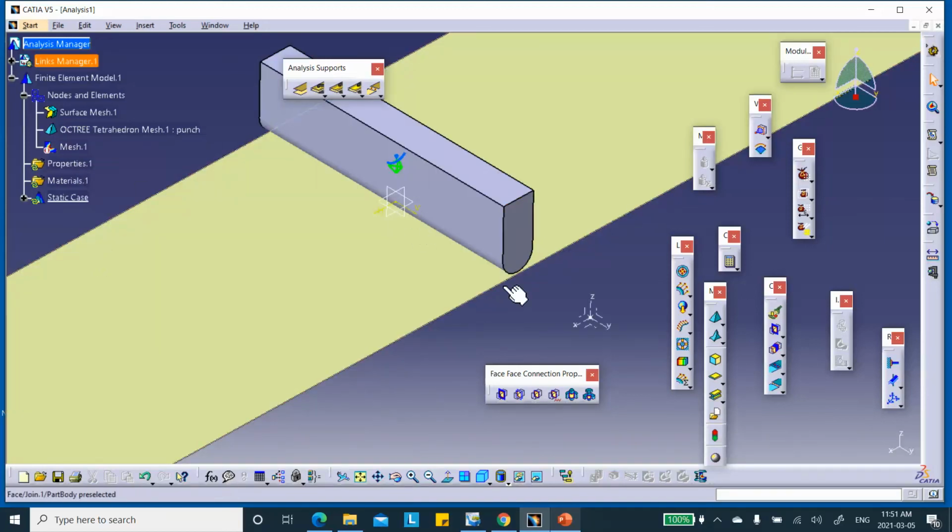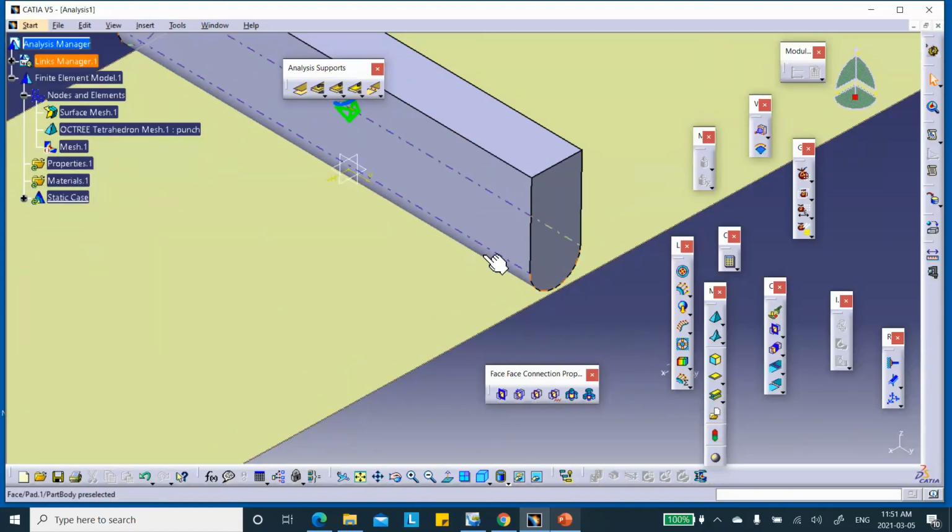Now how do I make a finer mesh around this bend? So if you go to the place that I actually meshed it with solids, if you look at the next toolbar, this one says local mesh size. See that right there? Local mesh size. If you want to see a little bit more about this, go to the FEA playlist and look under local mesh refinement.